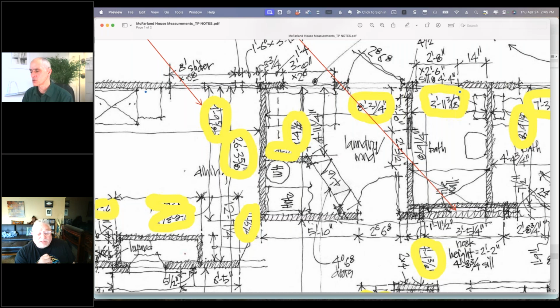I think if we know the area we're working in and we're not touching the other part, it doesn't really need to be that accurate. As accurate as they claim is good enough, and we don't really have a critical dimension in those areas. So I would just do dimensions that I know are critical, and maybe some overall ones to make sure the model's not really off on something.